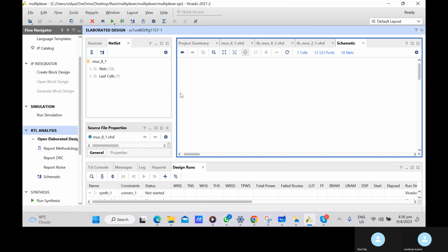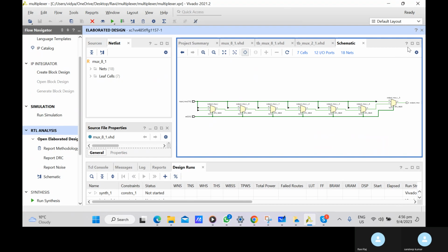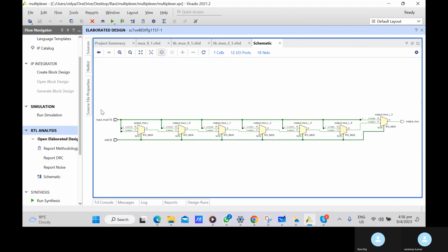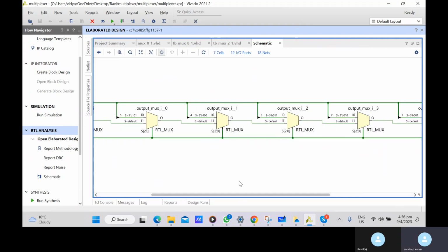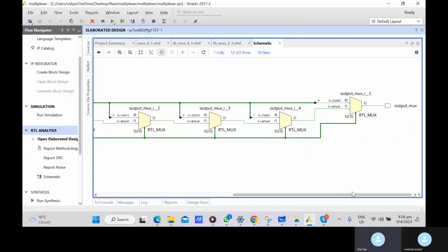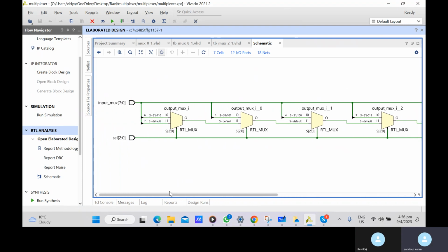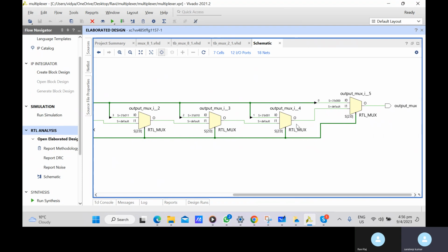See what hardware is there. It puts that in series. So it will always have a 2:1 mux, and it is basically a priority encoder. It has put the priority on the first statement.